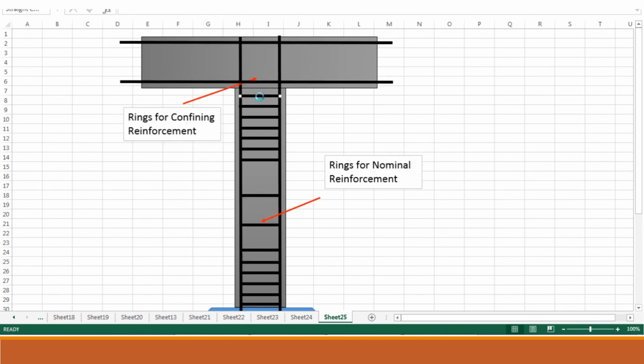Then we would have some reinforcing bars that are running perpendicular, similarly they would be provided in the other half. Now again we have discussed that there is a confining zone in the beams as well. So what we have, this middle portion, there is no reinforcing link provided in the continuous beam, continuous column joint. Okay, thank you.